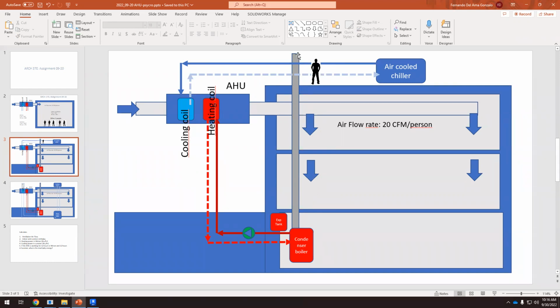So at least it should be like 7 feet. We have to extend the chimney about 7 feet above the roof level. That's the safest thing we can do. Even if the roof is not accessible, people doing maintenance can be up there and could be breathing the air that comes from the exhaust gas.